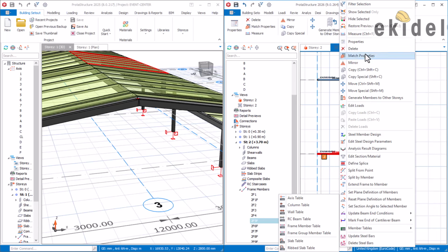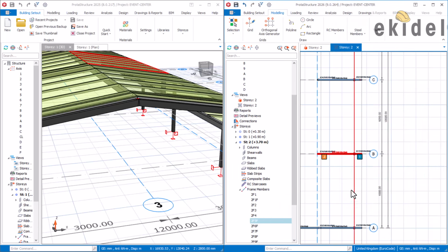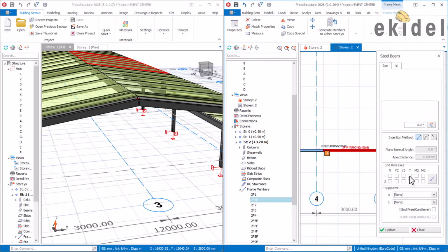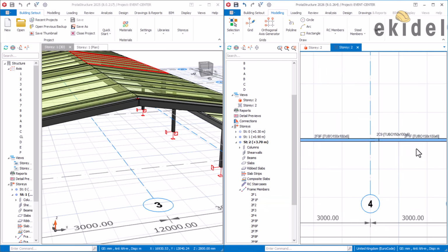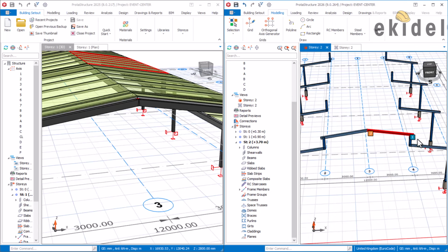Okay, that is fine. So come here and then come here, and then assign these two here, and then update, and then come to the last one now, which is the J here. Click on this, right click here, and the properties of it, and then come here, and the J. That's fine. Okay, that's fine. So we have assigned this now as cantilevers. Same thing here too. This other one too, because this J is also free, which is this particular end here. This small J here is free.